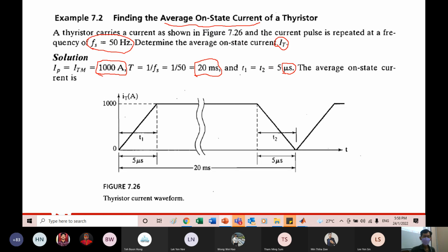So this is slower, and usually they are the same. Usually you will notice for a transistor, the rise time and fall time are a little bit different, in terms of 2 to 3 or less than 10 nanosecond. But like I say, in high frequency switching, that really matters. But at low frequency, this is so small, so it can be neglected.